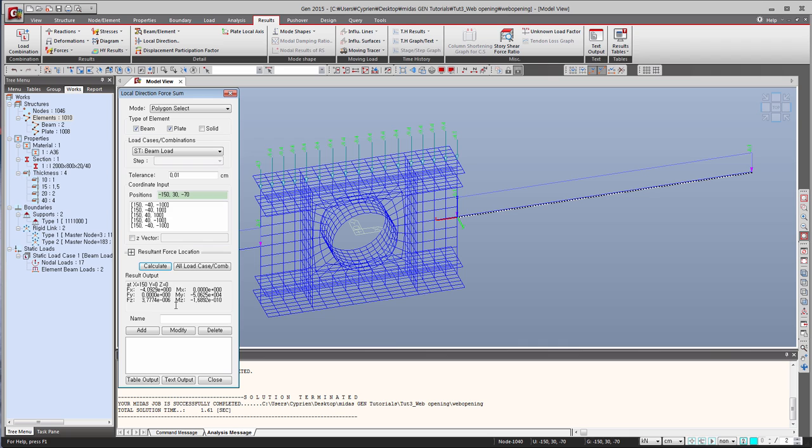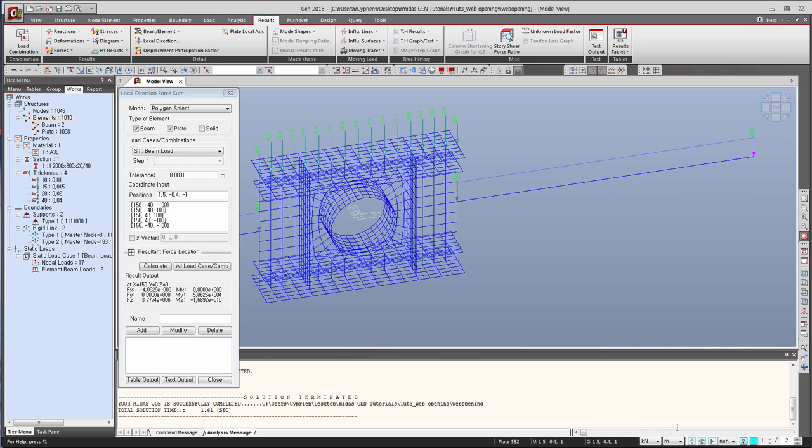This sum of all the nodal forces contained in a specific section is computed at the centroid of the section according to the local coordinates defined on the section for which element forces are to be computed. The computed value of the strong axis bending moment, My, for the member at the right end of the defined model is 506. So here I have to put again in meter, so you can see it.